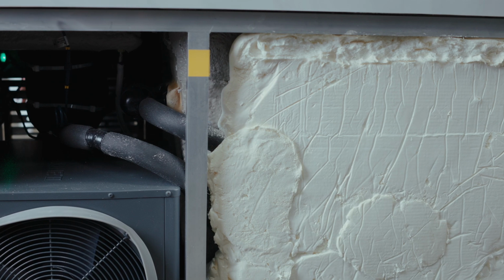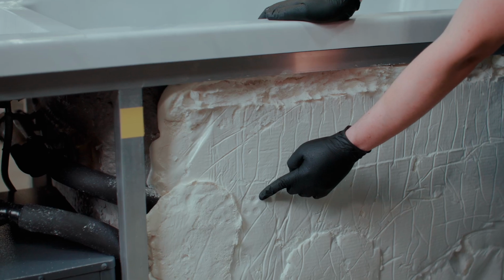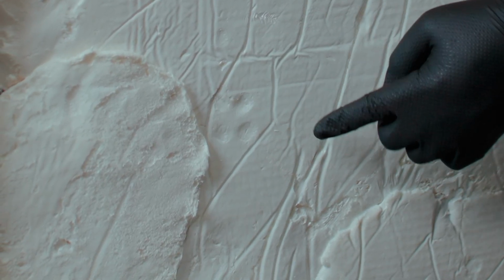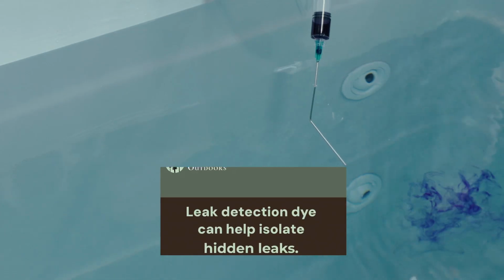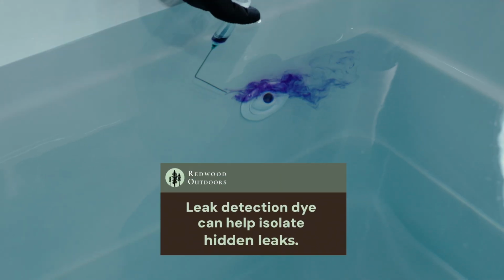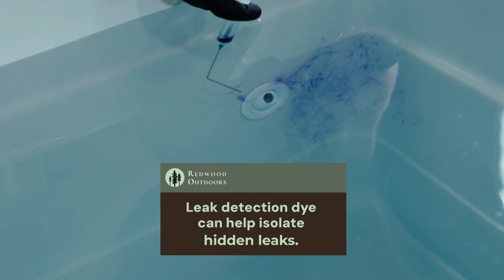If no leaks are found within the equipment bay, inspect the jets and lighting assemblies. These fittings are embedded within spray foam insulation and may require partial foam removal for inspection. If the leak source is difficult to identify, add spa leak detection dye to the water. The dye will naturally flow toward the leak location, helping narrow down the affected component before disassembly begins.